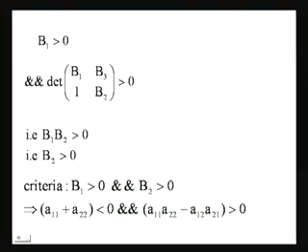So, anytime we do this, the easiest way is to write the characteristic equation for lambda. You can go the Hurwitz way also, but I find it a lot easier to write the characteristic equation. You feel a lot more confident about it, to be able to write the characteristic equation for lambda, and then require the two coefficients to be greater than 0.